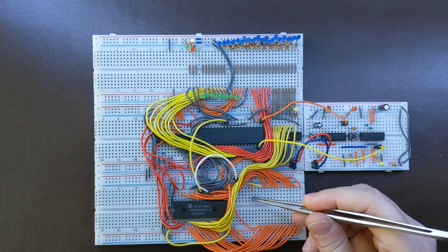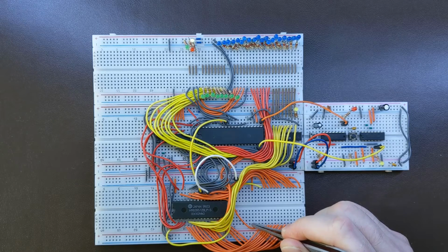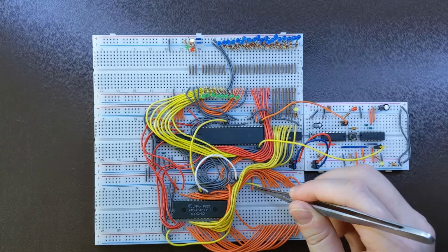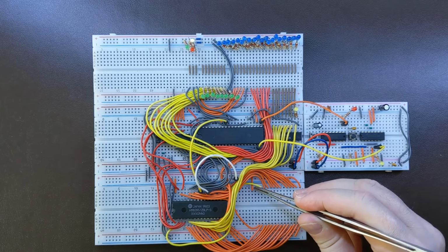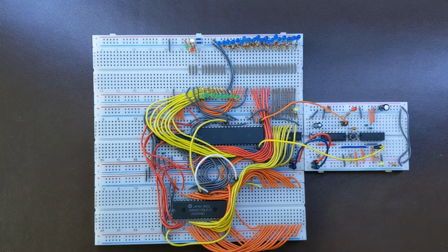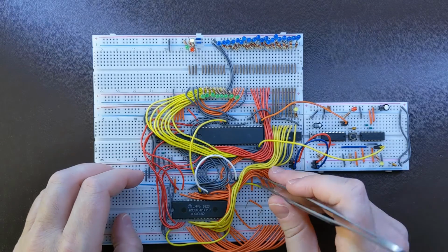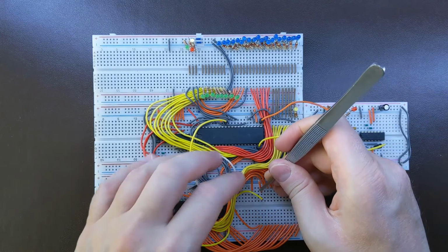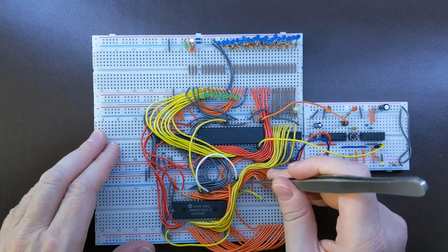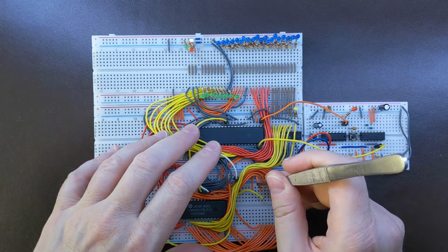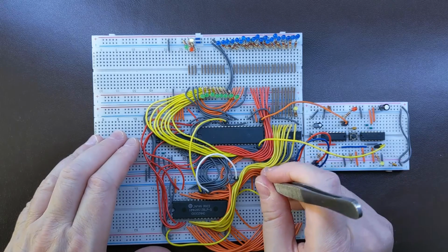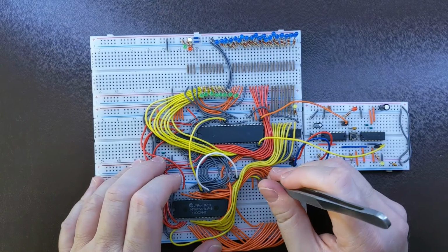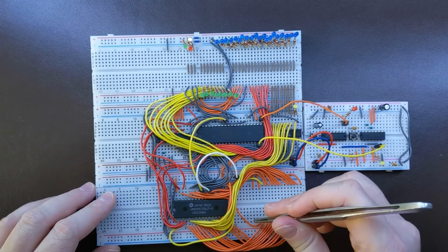Pin number 1 is not connected, as well as pin number 30 isn't connected. Pin number 31 is write enable, which we won't use, so we need to short it to VCC. We're not planning to program the flash memory in system. If I take this out for a moment, then add this to VCC and pin 30, then this can go back. This is not connected, this is not connected.